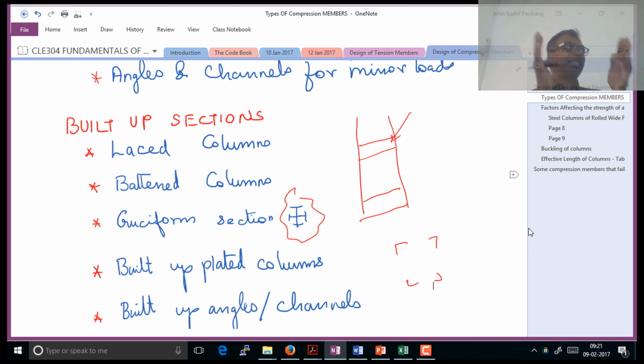So if suppose I'm wasting 1 meter of a 200 kg per meter column, that 200 kg becomes scrap. On the other hand, the same effect could be got by say 4 sections with 20 kg per meter run. So 80 kg might have been the wastage when you use individual elements. Connecting a very big section is very difficult.